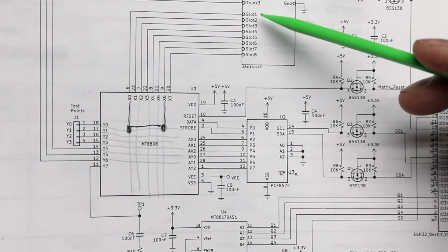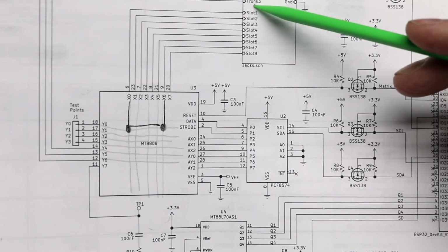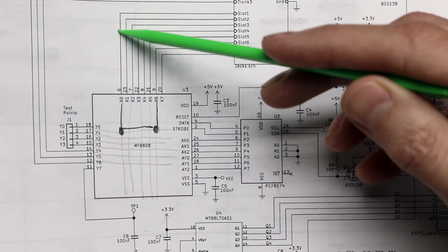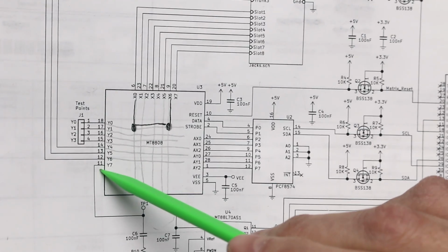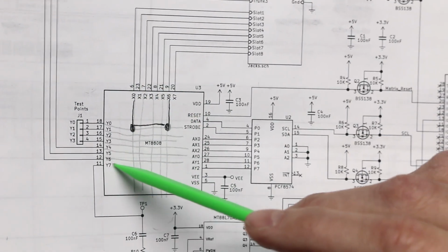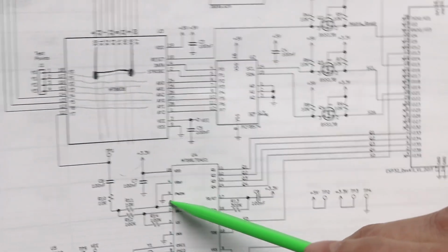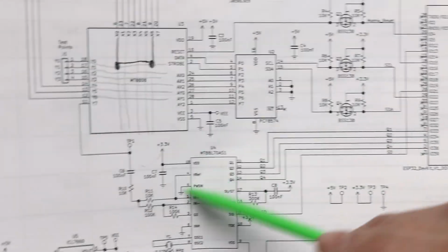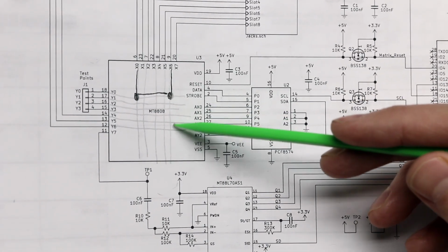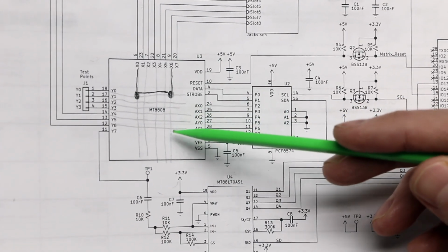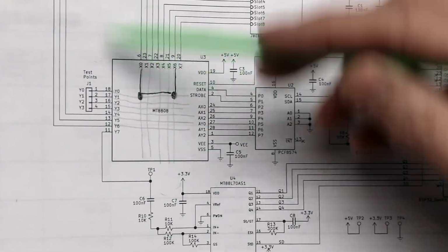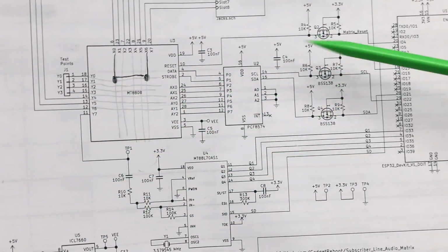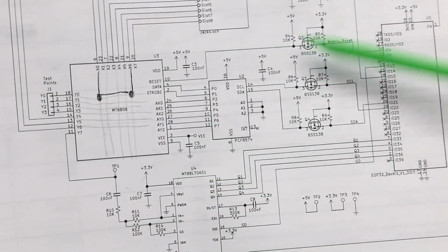So that's how we make a telephone audio connection after a call is placed. So if I wanted to listen for DTMF touch tones from a phone plugged into this line here on X0, I would tell the chip to also make a connection at Y7. So then X0 comes to Y7, and that's connected to the DTMF decoder, and now the ESP can listen for touch tones. So in previous projects, I've used a similar product, the MT8816 instead of 8808, which is an 8x16 matrix. So I talked more about how all this works, and none of this is really brand new stuff. So I just wanted to do a high-level discussion.